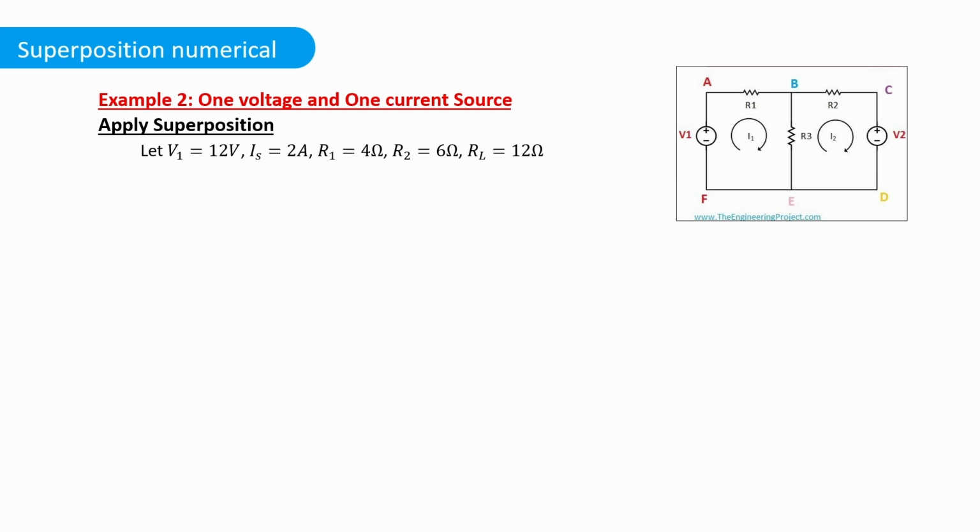So for the second case, we will use this current source, right? This is the current source. I'm using the previous diagram, so I have to update it again and again. Now the diagram will be updated because we are dealing with the second source and the first source will be inactive. So when this becomes inactive, since this is a voltage source, this will become a short circuit.